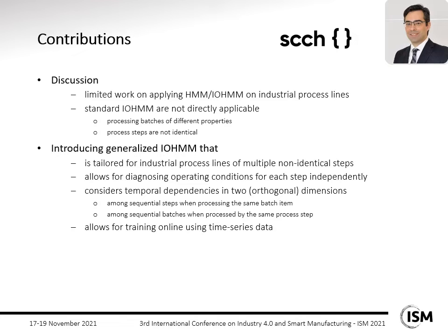Now, this methodology allows for diagnosing over operating conditions for each step independently and considers temporal dependencies in two, let's say, orthogonal dimensions. In particular, we consider temporal dependencies among sequential steps when processing the same batch item. So the state or the operating mode of one step influences the operating mode of the next step as the same batch item is processed.